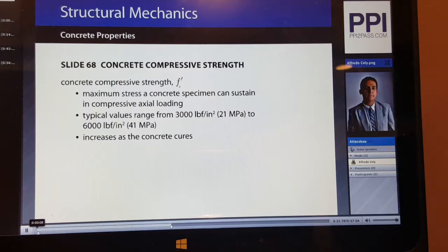The cylinders can be crushed earlier, and that determines whether the specified strength has been met. If we crush cylinders at 7 days and the compressive strength was 4,000 psi or greater, then the contractor will have the green light to move on to the next construction task.